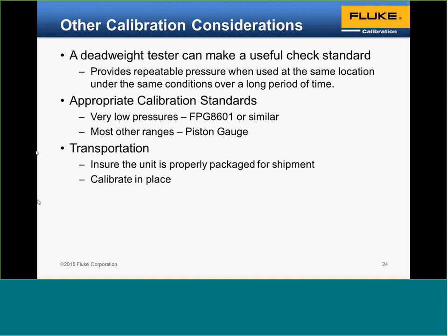But with pressure controllers, do consider that there are other options, either calibrating it yourself with your own reference standards, or having a provider come in and calibrate it at your facility.